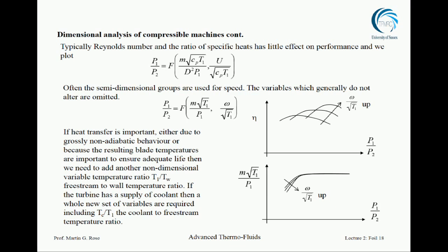And the reason they do that, I was once asked the question, why bother? It's going to stop anyway. And the answer is it saves time, because they can get to the gate faster if they can stop. And that time is about 10 minutes. That time is long enough that it's worth having a thrust reverser for that reason. Because it's following the logic of carrying the kit you don't need. Carrying a thrust reverser, which is a sophisticated kit, is doubtful. But the airlines like that 10 minutes of extra time.